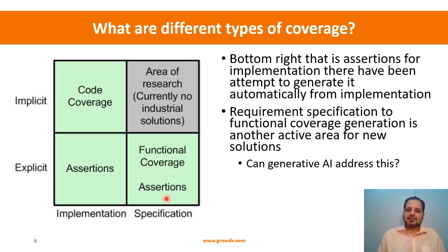So those are requirements that are being covered using assertions, as well as the microarchitecture implementation can also be covered using assertions. But additionally, for requirements where the stimulus is being generated from the testbench, and then the monitors are monitoring certain activities on the signal level and generating transactions, when you do coverage using those transactions, you generally do it in the form of functional coverage within the class based world.